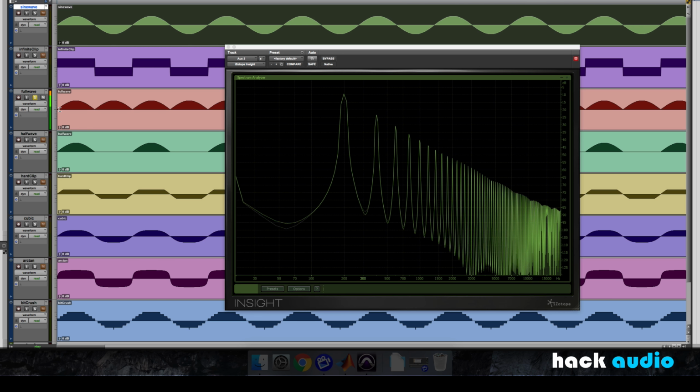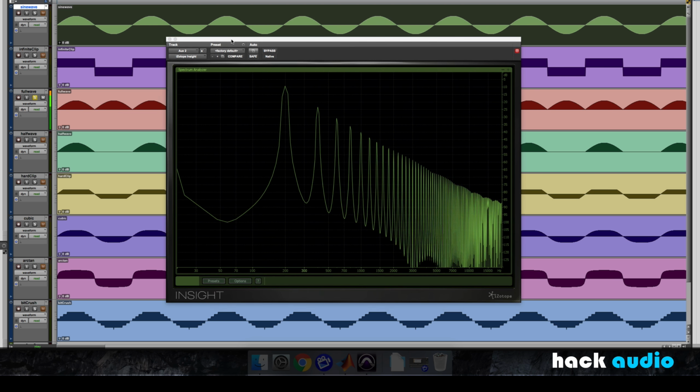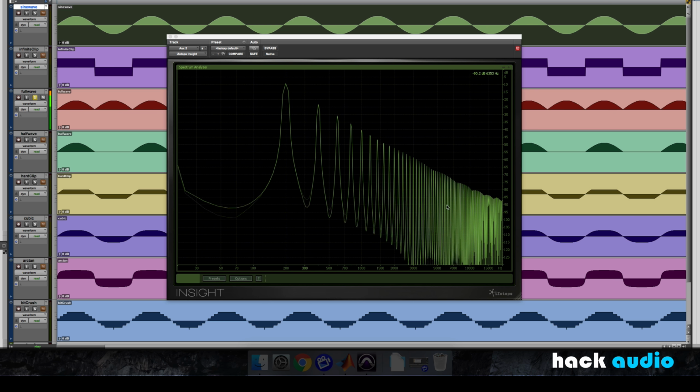In this case, the pattern that gets created here increases in amplitude to be positive, then it starts a new cycle over again. That's going to increase in amplitude and so on. So in this case, our period is actually half the amount of time. Therefore, our frequency is actually going to go up. So now the lowest frequency is 200, or twice the original frequency of our sine wave. So that's a function that gives us even harmonics.